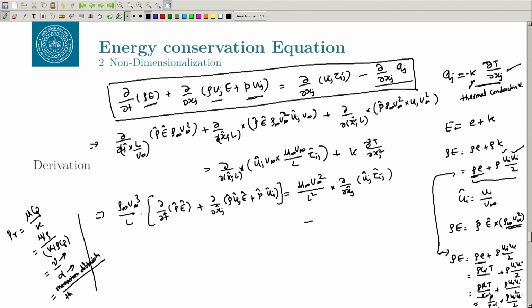By thermal diffusivity. So, this number is very important. Let us say you have a solid surface, and the solid surface has certain conductivity and there is a flow happening on top of that. So, the heat transfer will take place. There will be diffusion due to the momentum and diffusion due to the presence of the conductivity. So, the Prandtl number defines the ratio between the two.